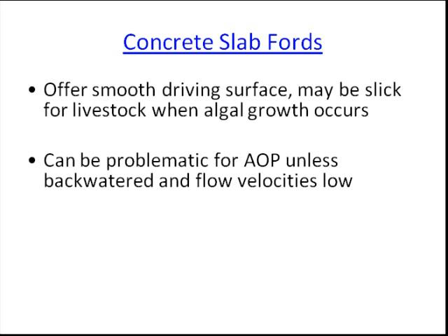Sometimes low-flow passage slots are incorporated into slab fords, but these can be pretty hard to maintain and tend to fill up with bed load. Passage slots sometimes self-scour at higher flows, but problems generally arise during low flows when deposition in the slots blocks access and organisms are forced to try and negotiate the slab surface.